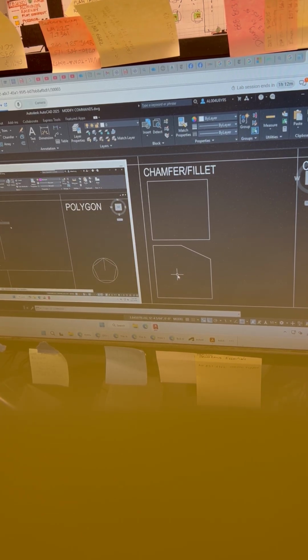All right. Go to the radius option, radius, and set the radius to 0 and hit enter. I'm going to try to remember this. I want you to hit multiple. And now go around this top thing here and select each of the lines and watch what happens. Look at that. They come to a nice corner. Select one line, select the other line, and see how they come to a nice corner. Same thing over here. A nice corner. Same thing over here. A nice corner.